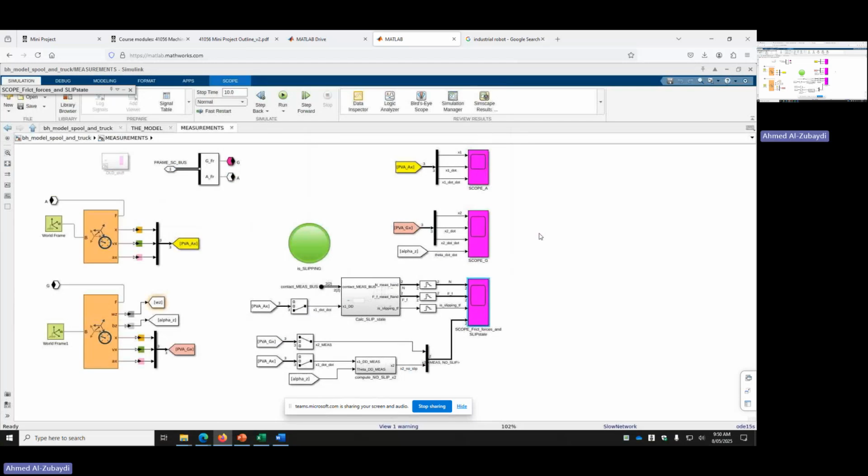Okay, so later what you need to do is just change your parameters, have something like 2 or 3 sets, do the calculation for one of them, take the results from here, and compare them with your hand calculation. Then you say, okay, now the code is verified, and you start to run the other cases and make a comparison between different cases. For example, the bigger the mass is, the bigger the angular acceleration is. The bigger the mass is, the less friction force, the less slipping possible, and so on. Okay, so that will be your first part.